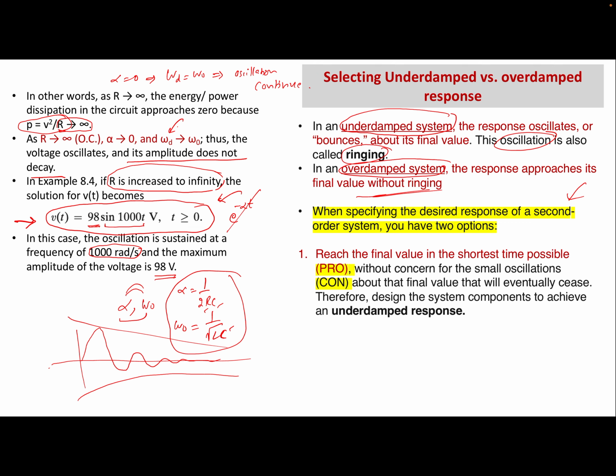Okay, so this is what we have. If you were to solve any circuit in terms of an underdamped response, and you are looking at the natural response of a circuit, all you need is this. You find the initial conditions. You determine the values of alpha and omega naught. You find out which response it is. In the case of an underdamped response, this is the equation that you have for the response, which you don't need to rederive when solving the circuit. You just need to fill in the variables. The omega d equation is this, and the B1 and B2 equations are this. So you can fill out all of these variables and you get a response.